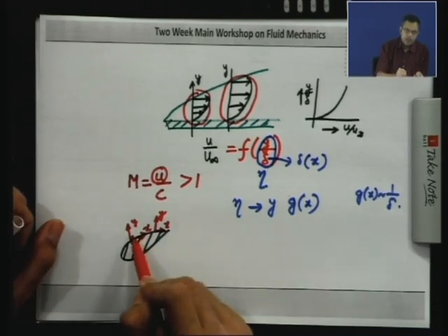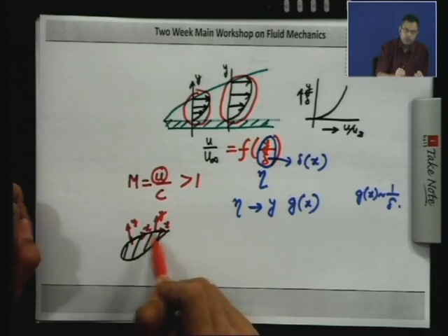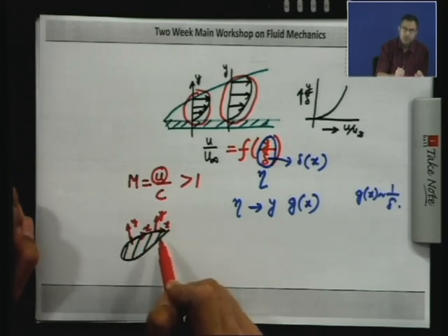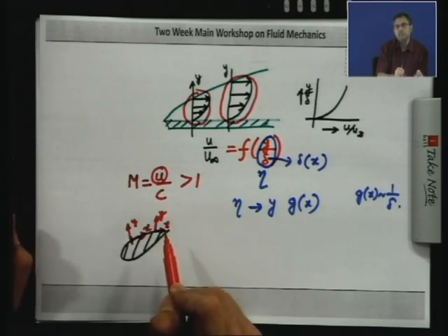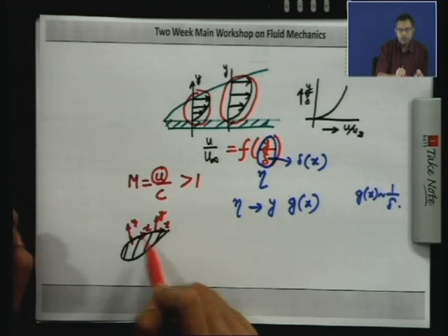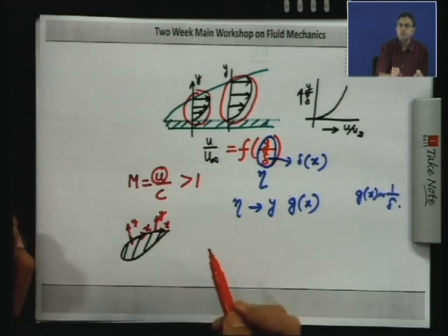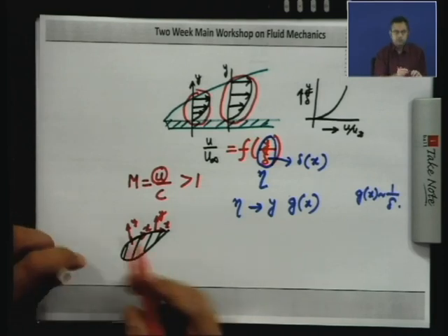But x and y are called boundary layer coordinates and they are fitted to the shape of the body. For a curved surface, not just an aerofoil but any curved surface, x and y will vary continuously; that is the first change. The second change is that because of the curvature there can be an adverse pressure gradient which may lead to boundary layer separation, and then boundary layer theory can no more be used.